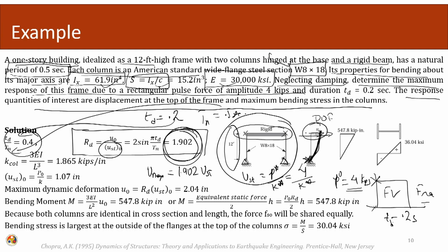The deflection at the top for a cantilever is given by P L cube over 3 EI. So, P equals delta times 3 EI over L cube. If we take delta as unit, then the force required to cause this unit deformation will become my stiffness.